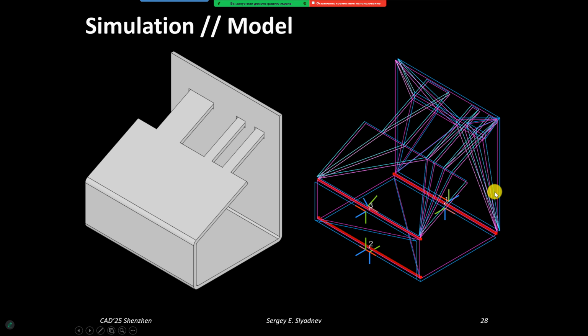So our take here is different. We use the information about the recognized sheet sides because we already know the inner shell and outer shell of a sheet metal, and we can take just a sparse triangulation out of the analytical surfaces, and we can use this triangulation for collision tests. And here we actually ignore the presence of thickness faces. We just eliminate them from the simulation model.